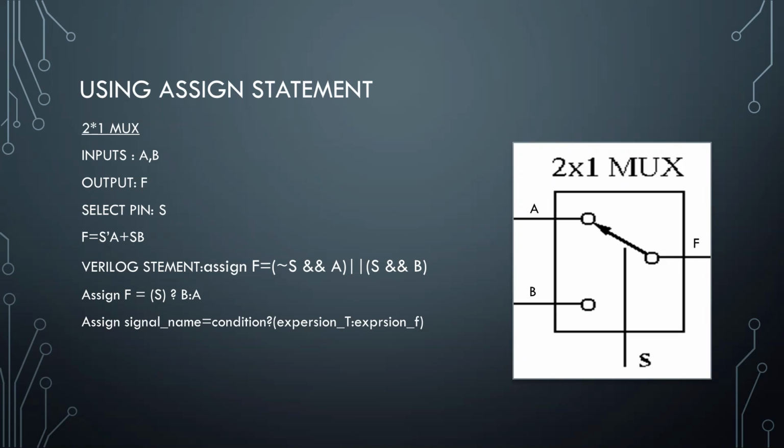So we can write the Verilog statement as the OR of S bar ANDed with A, and S ANDed with B.